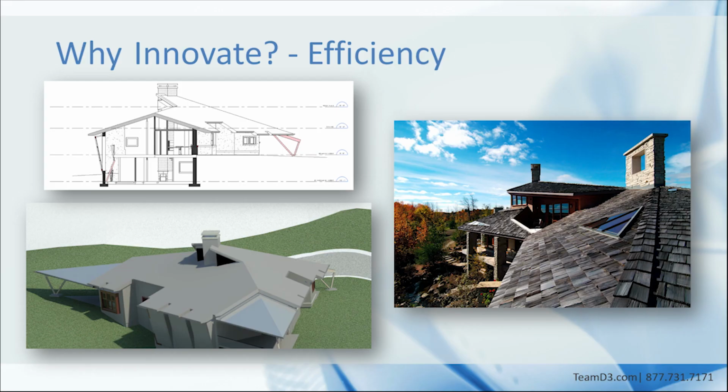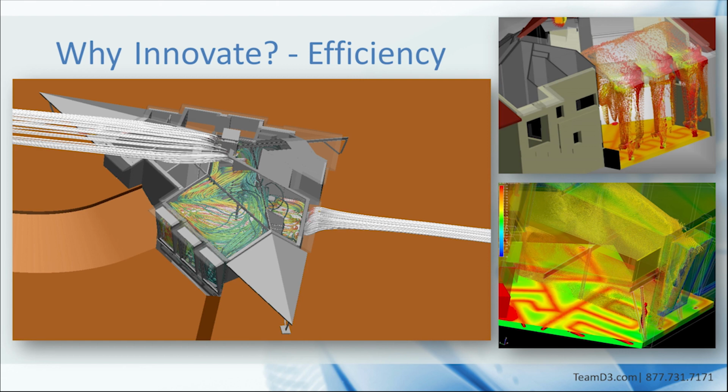The challenge with these types of systems is to validate your innovation. Hot and cold air collection systems are very custom to the architectural design of the building. There's often a trade-off between form and function that has to be studied and optimized early in the project to ensure success. If you have never done it before and have to get it right the first time, then CFD is a must-have and one of the first things you should do.